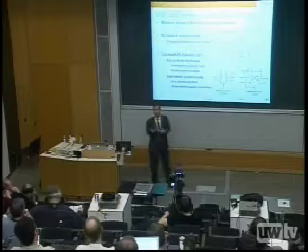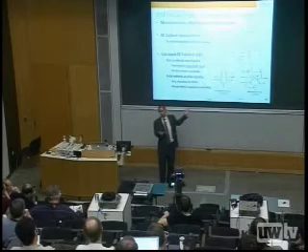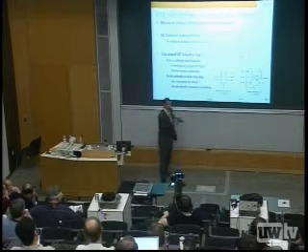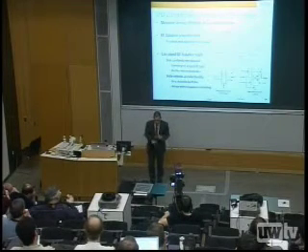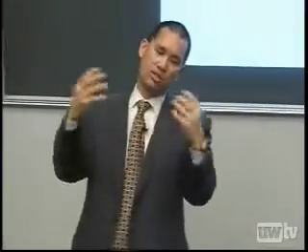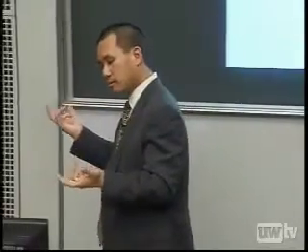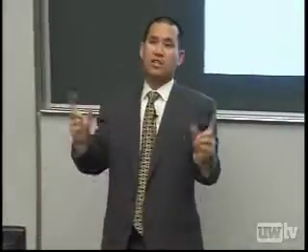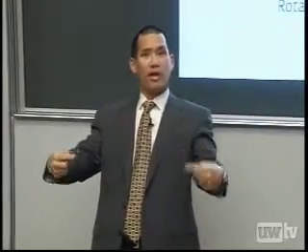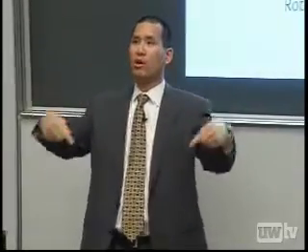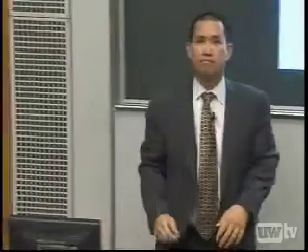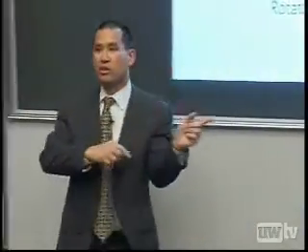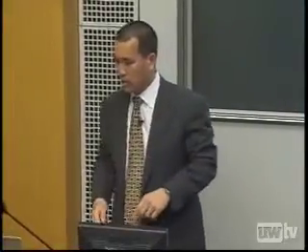I can do a refresh scheme where periodically I refresh these nodes and sort of halt communication temporarily. That's architecturally inconvenient often because now you have to shut the system down, but I can hide that by saying for every 64 data bits, I have a 65th channel that's refreshing. And I rotate which channel is refreshing periodically so the endpoints have no knowledge of this ever happening. By the way, please interrupt me if you have any questions as I go through this, or I'll just sort of keep going. All right, so the circuits are pretty simple.